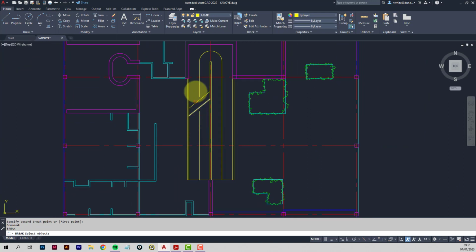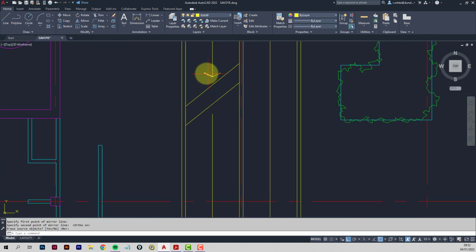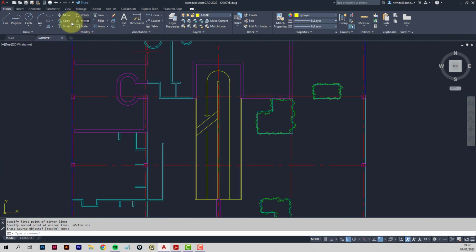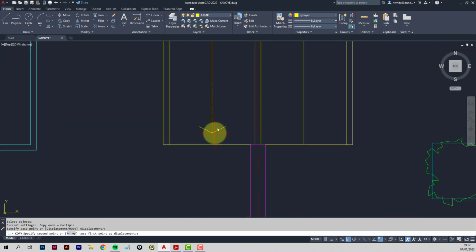Okay, and what I want to do now is put an arrowhead onto this, so just a line will do. O snaps back on. Okay, and then mirror that so it looks even and tidy. I need ortho on to help me do this. Okay, just drag downwards, enter to stop, and I can copy that arrowhead down to this position. So copy, try that again, copy, pick these two lines, enter, from end point to end point.